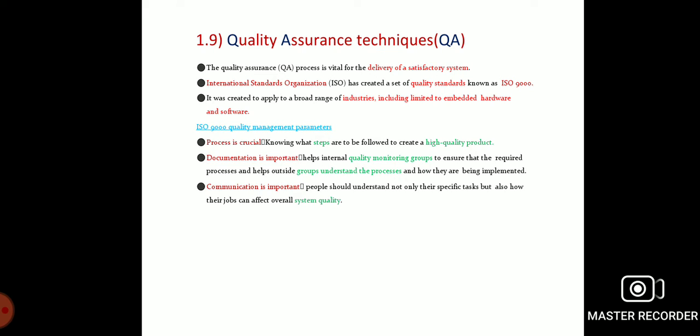Now the reliability, that is burn-in testing. Once the above tests have passed, perform some burn-in tests with different scenarios and possible worst case scenarios. Depending on the type of product, you may consider a 7 day reliability test to be long enough.